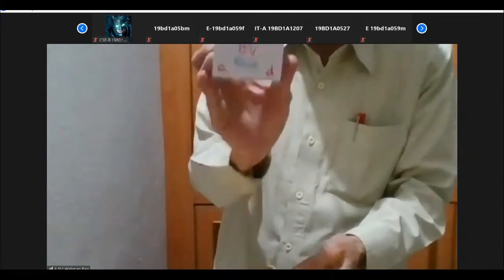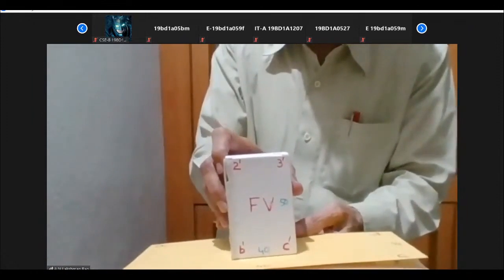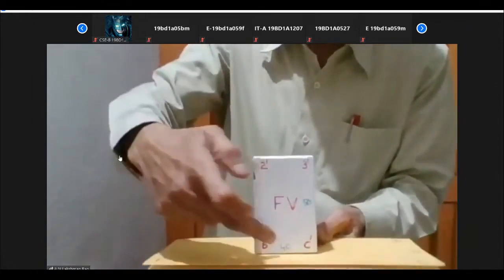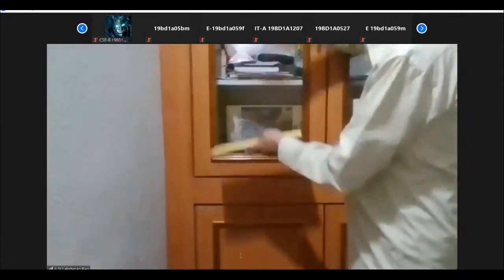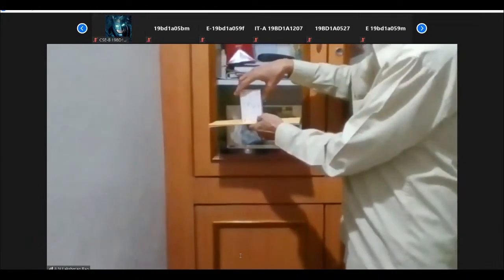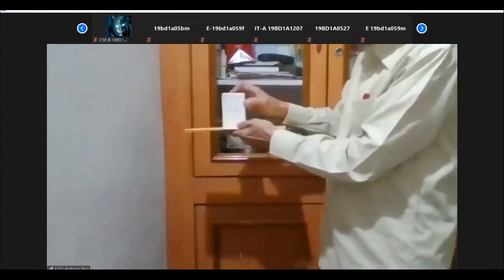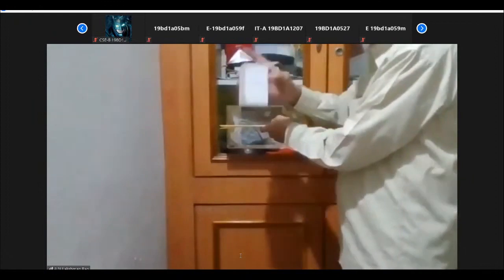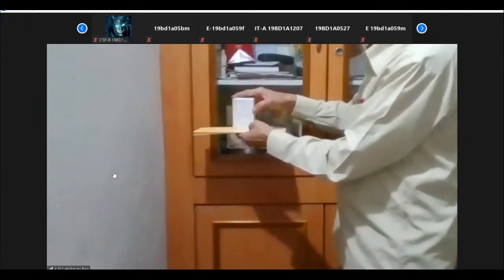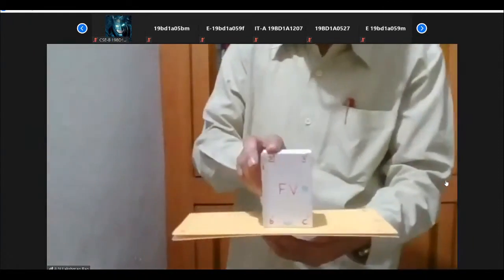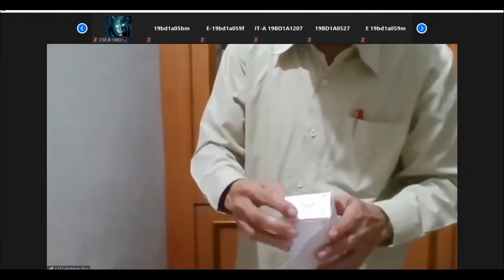This is the base. The base is resting on HP, and he says one side is parallel to VP, like this. This is the vertical plane. This line B dash C dash is parallel to the vertical plane. So this is the position: HP, VP, solid. The base is standing on this, such that B dash C dash is parallel to VP. Now he says for this I have to draw a development.